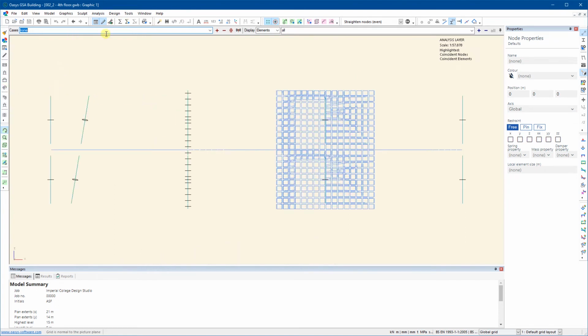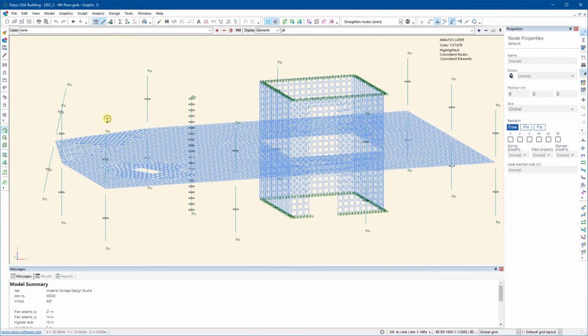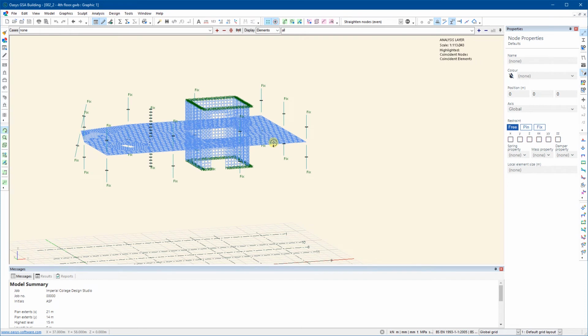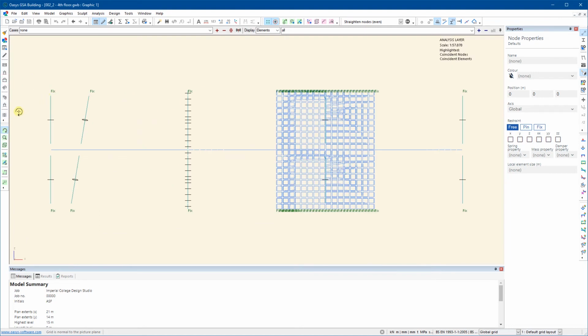So it's not analyzed, obviously, so maybe I want to put in my restraints. So when it's extracted it, by virtue of me telling it it's a submodel, it's already put in the restraints. I don't like having the tops fixed. Essentially, that means it's hung from above.